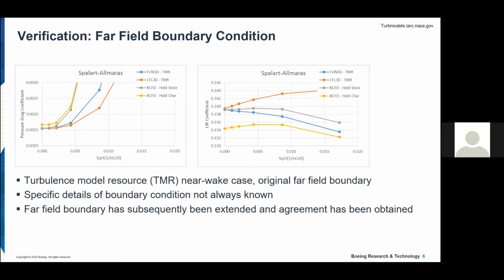A lot of times when we're trying to compare to other solutions, or possibly even to analytical data, we may find that the boundary conditions are not implemented entirely consistently. Although they qualify as the right type of boundary condition, there may be differences that end up leading to some of these problems, where you would tend to say, okay, this is not verified, there's something wrong.